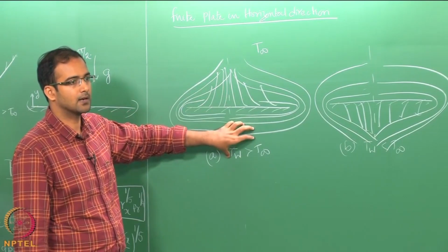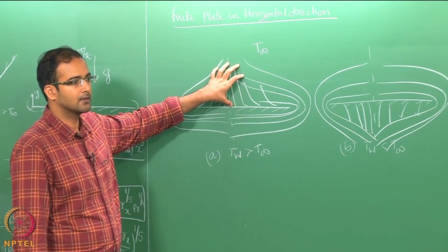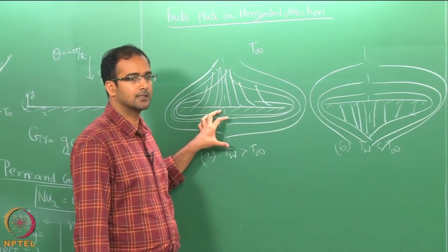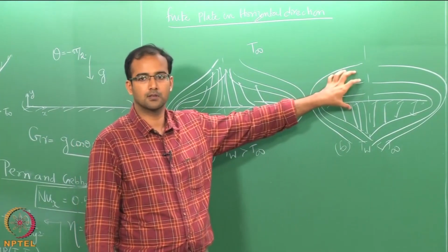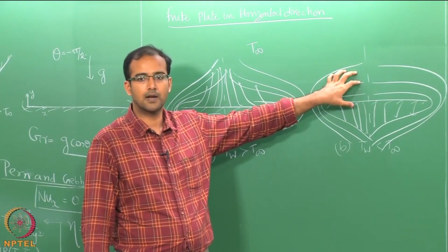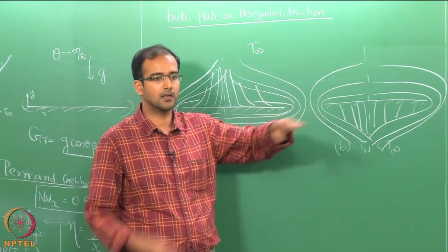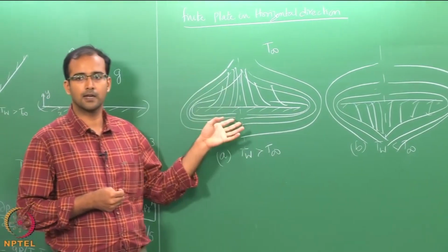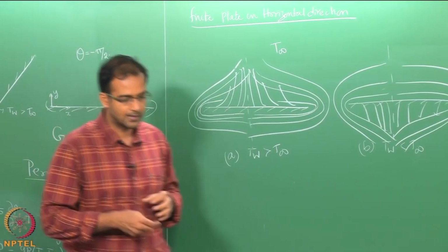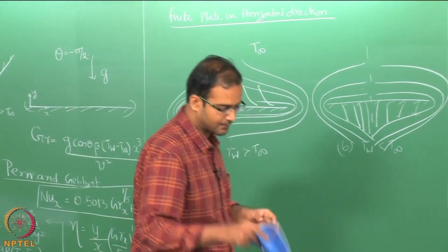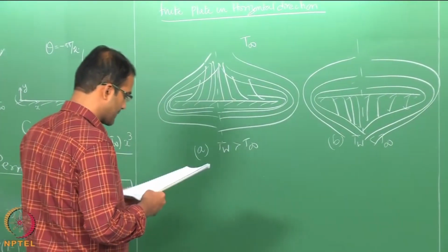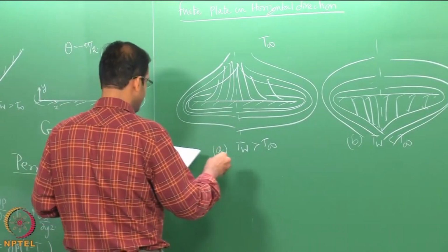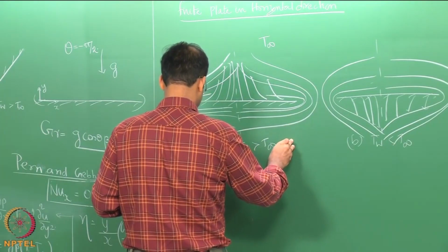other pattern which is this one, and the same pattern for this can be used for this also, and similarly the Nusselt number for this pattern can be used for this also. So, now obviously you should understand that the Nusselt number for the top and bottom surfaces will be different because the flow patterns are locally different. Okay. So, I will just give the correlation. These are obtained from some experimental observations. Okay. So, let us identify this region to be so